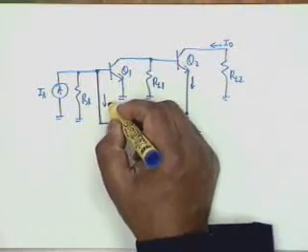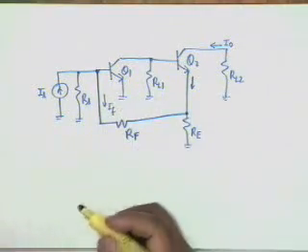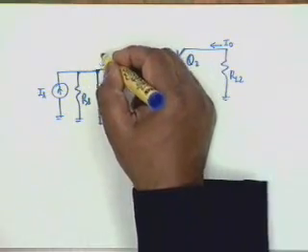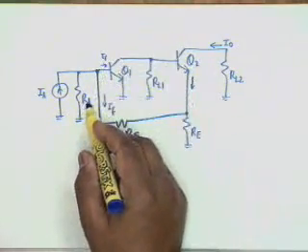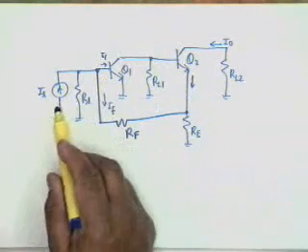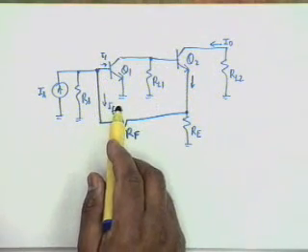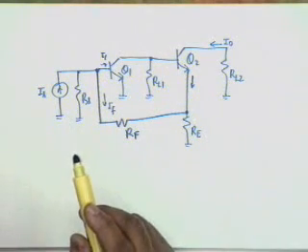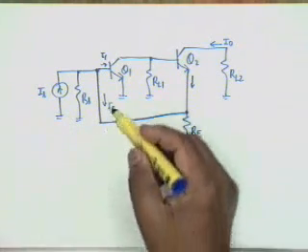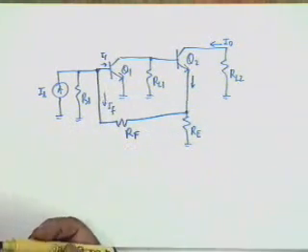Now what is the kind of input connection here? Series or shunt? Series. Okay. Let this current be IF. This current II, if RS is not there, is obviously IS minus IF. So it is negative feedback. How do you know it is negative feedback? Because I could have drawn IF in the other direction also.